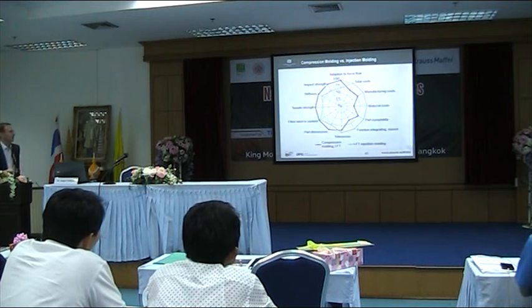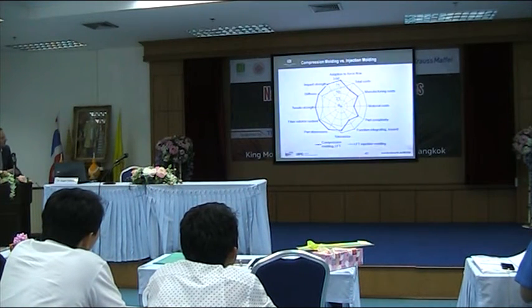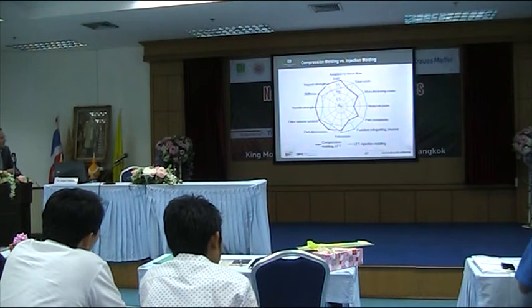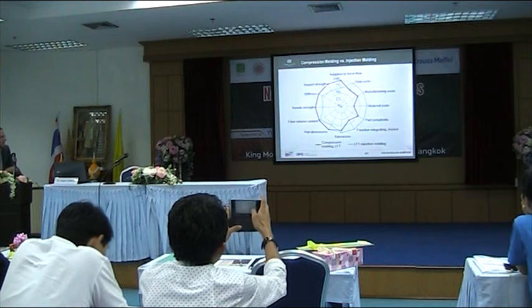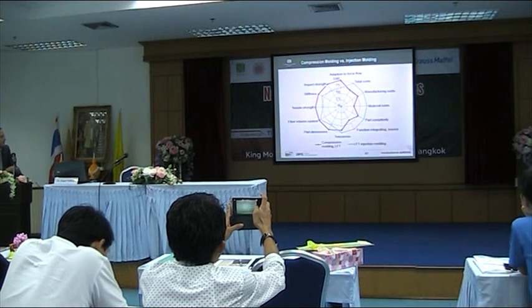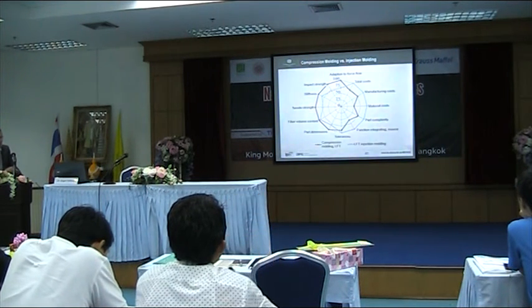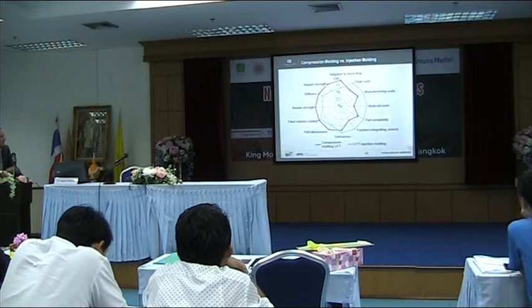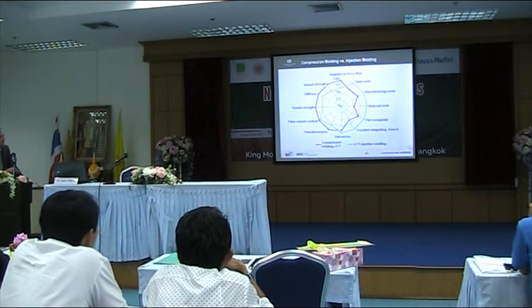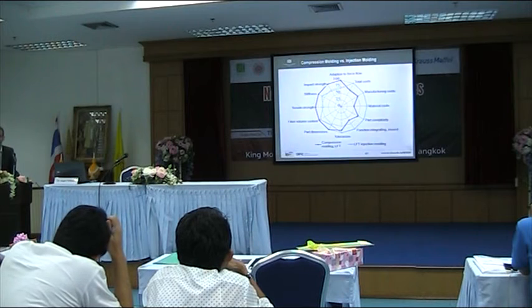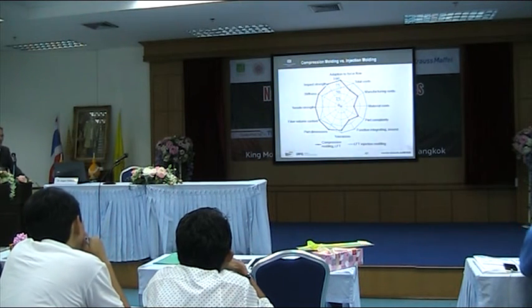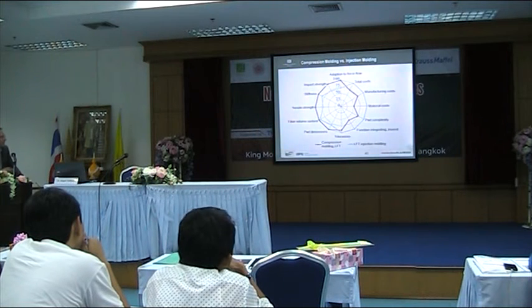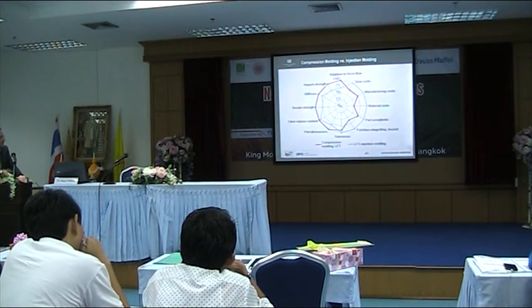So looking at the properties you can reach, compare compression molding with long fiber thermoplastic and injection molding with long fiber thermoplastic. What we can see, summarizing in red, is that compression molding is better because of the longer fibers you can reach in the mechanical properties. Injection molding is somewhat better in the efficiency of the process and in the cost because of the shorter process. You can make parts much more efficiently with it in the cycle times. You can additionally integrate some functions and so on.